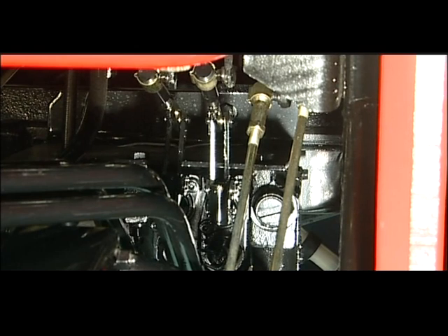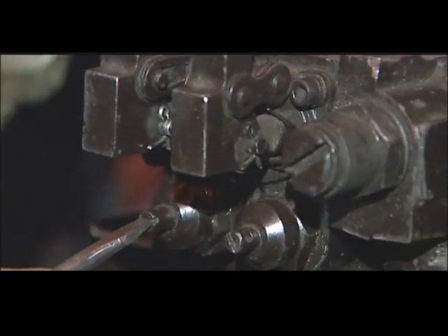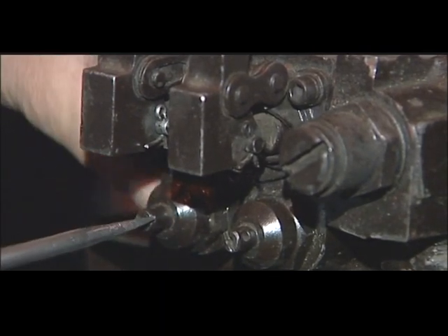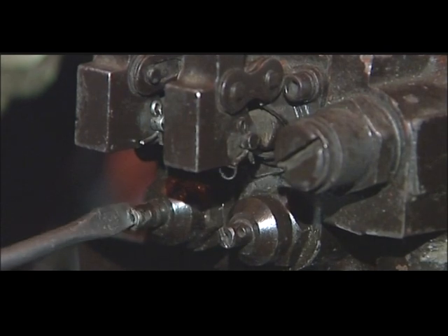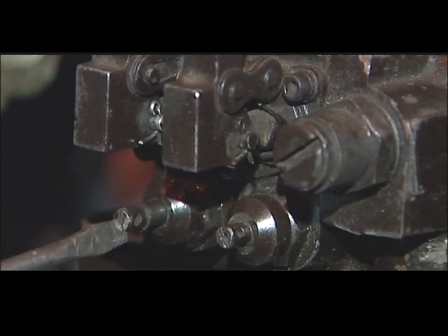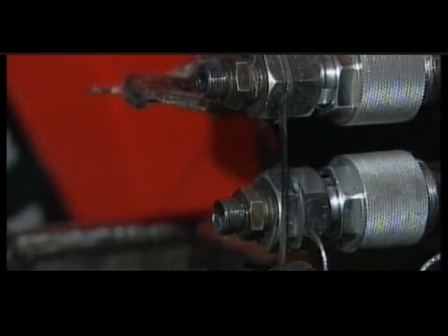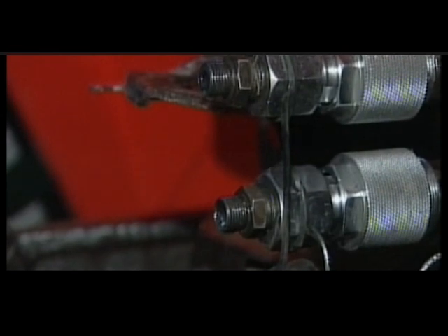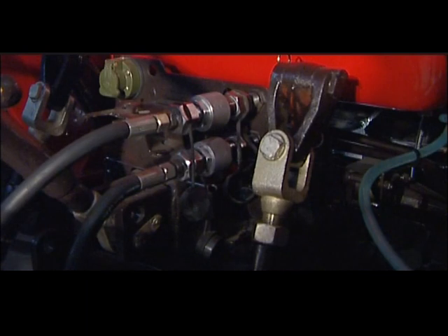The upper chamber of the dual-action oil cylinder will receive the oil. The lower chamber will return the oil, or vice versa. The upper chamber returns the oil. The lower chamber receives oil. When a single-action oil cylinder is used for the implement, loosen the single-double function knob on the multi-way valve. The multi-way valve matched is used as single-action.